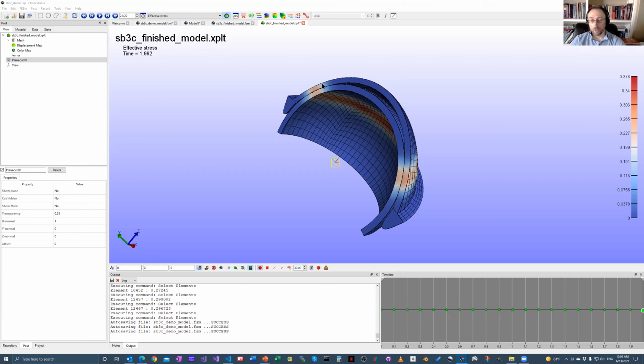So I know people have gotten around that by writing their own scripts that map image data to their mesh once they have the FEBio input file. And then once you have the input file, you can bring it in FEBio Studio and the mesh data will be preserved.